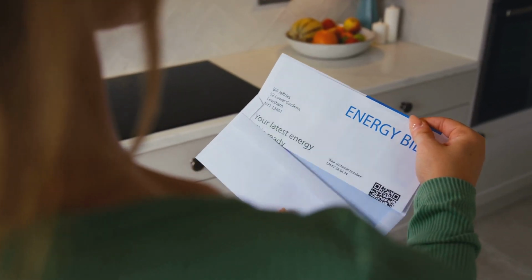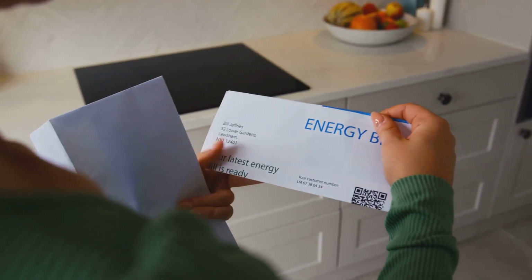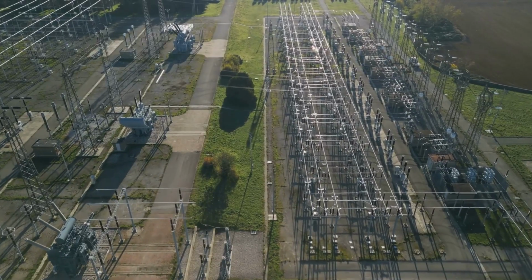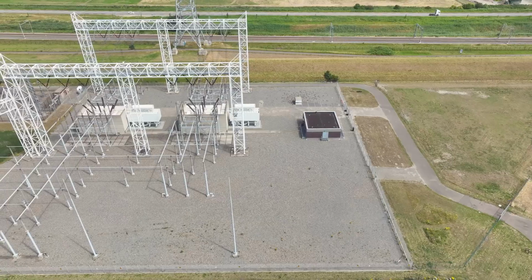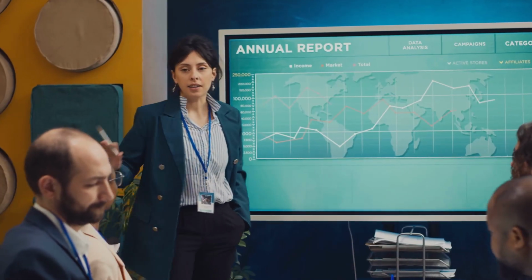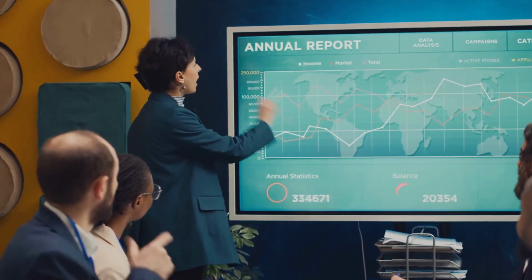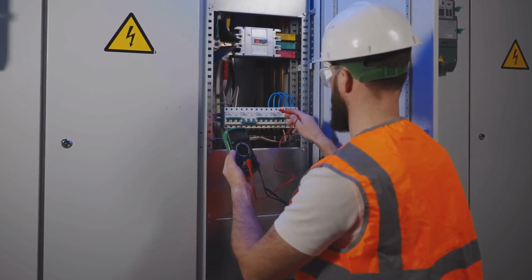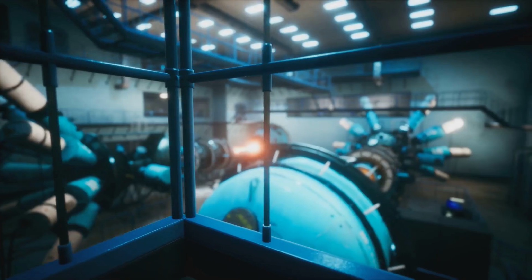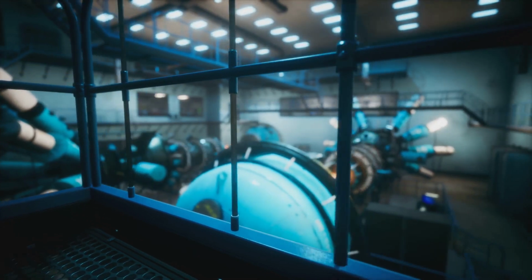Reactive power charges are fees added to the electricity bill by suppliers of those with a poor power factor. They do this to help cover the costs of the distribution network, which can increase when a large amount of power is wasted. A site that pays an annual reactive power charge of £20,000, for example, could potentially eradicate that charge by investing in power factor correction equipment. They'd save costs and add operational resilience.